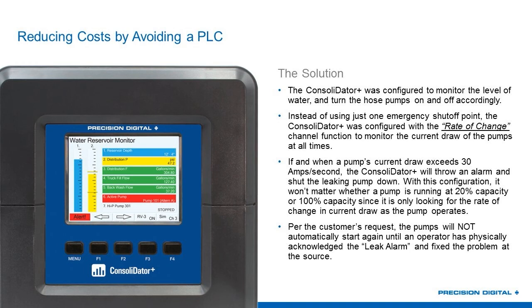Now, the last part of this particular application is the way I had it originally programmed was that when the alarm condition was cleared, it would start the pump up again automatically. Customer didn't really want that, so I changed it, and we made it so that an operator had to physically come over and acknowledge the alarm and fix the problem before the pump would come back on.